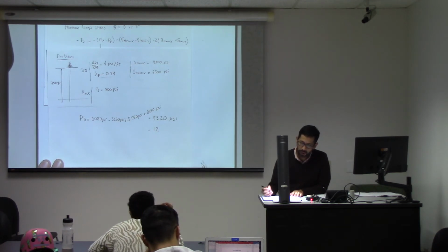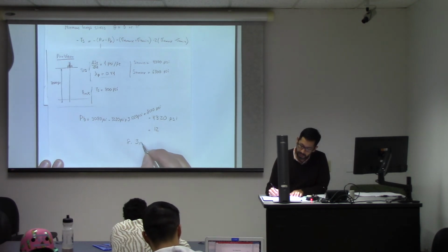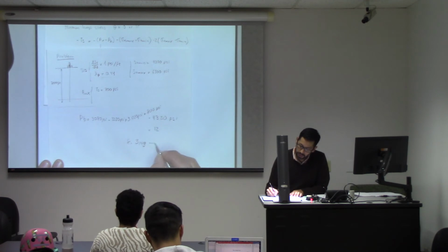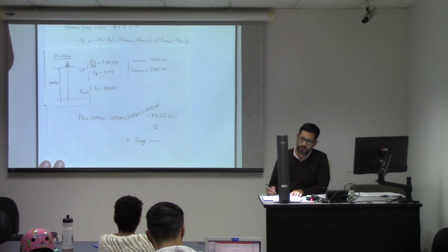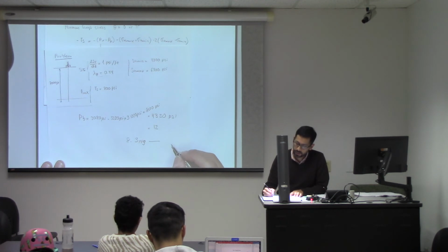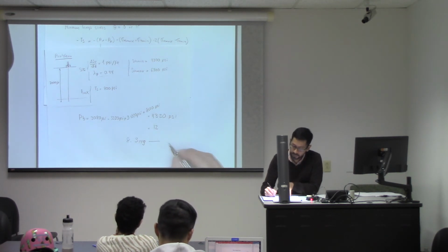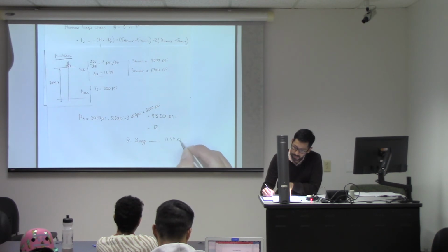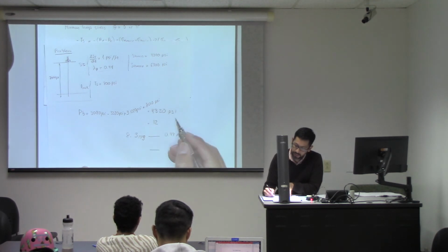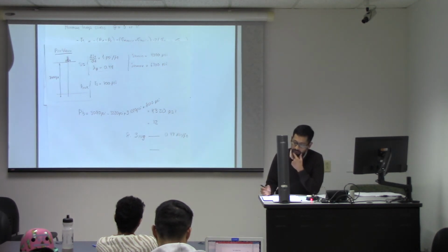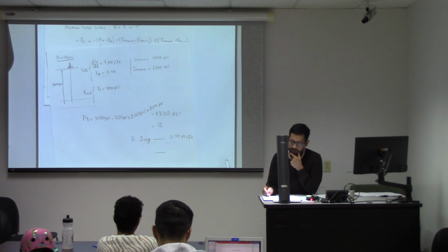Well, we know that a hydrostatic 8.3 pounds per gallon is equal to a gradient of 0.44 psi per foot, right? So if you divide this number by the depth, which is going to be, what is this divided by 7,000?